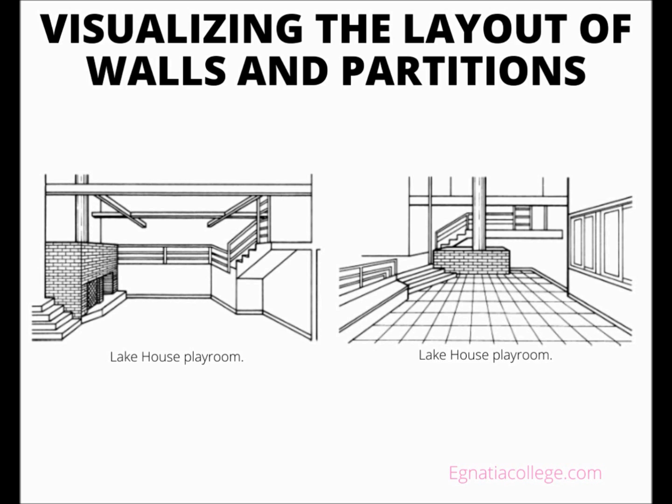A broken line in this area indicates the edge of a floor above. These floors can be seen more easily on the first floor plan. Also notice the location of the fireplace, which will extend up through the upper floor. The L-shaped stairs lead up to the first floor.